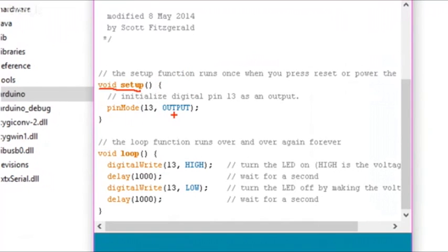That is for initializing the pin. So pinMode, as I already told you, P should be small and capital M. 13 pin output. So I told in digital, in Arduino there are 14 pins, 0 to 13. Those pins are digital input/output pins. You can define them as either output or input. So the 13th pin I am just keeping, let it be output pin. So pinMode 13 OUTPUT.